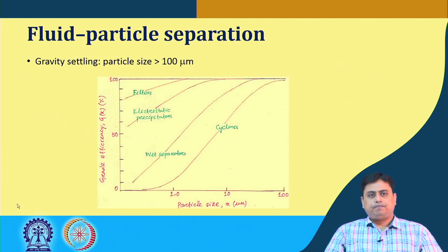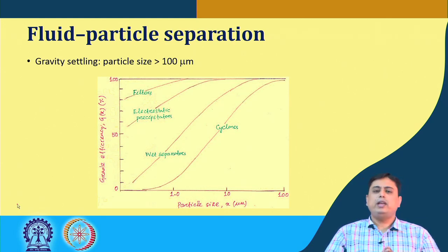So, in this section we will focus on both aspects, and we will start with the first option, where we have a fixed vessel and a fluid entering with a high tangential velocity. Such an operation we call a cyclone separator.